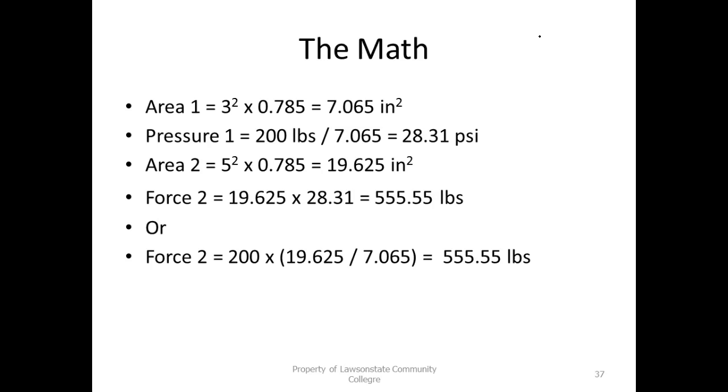What's the size of the cables running from your battery? And what's the size of the ones running to your speakers? They're a lot smaller, but they're delivering that power at a lot higher voltage. And of course, amps is equal to P over V, so the higher you can make your output voltage, the less current is going to be required to produce that power.